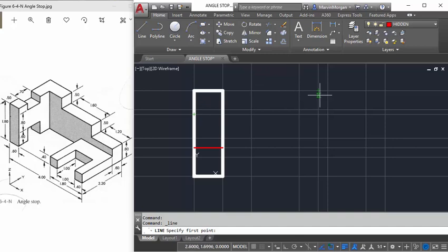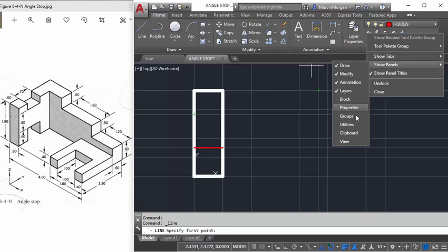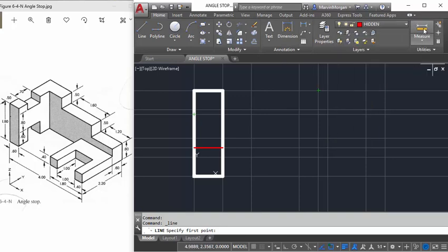If you have a difficult time understanding these lines, my suggestion is to use your utilities button and get your measurements that way. So on my screen, I'm going to go to my show panels and get my utilities back. You may already have it in your display. So I'll click my measurement button and go from this point up to determine what height do I have. So at this location, I'm at 0.70. So I know it's the next line I got to draw my red line. So from here, I go across, and that would represent my two hidden surfaces behind this wall.